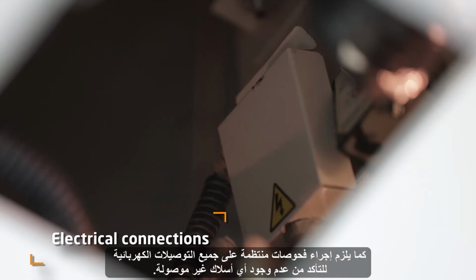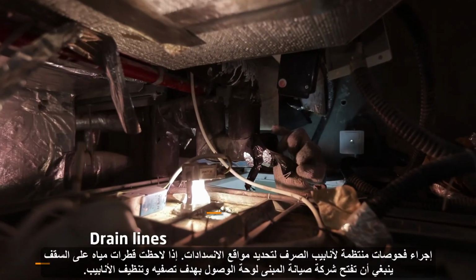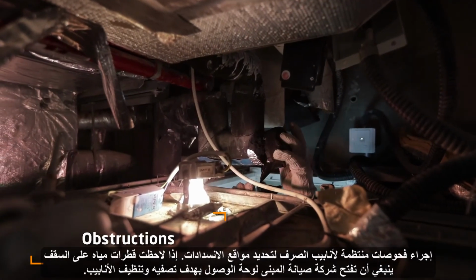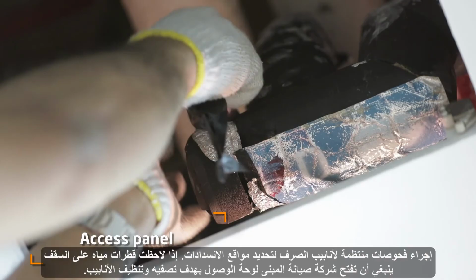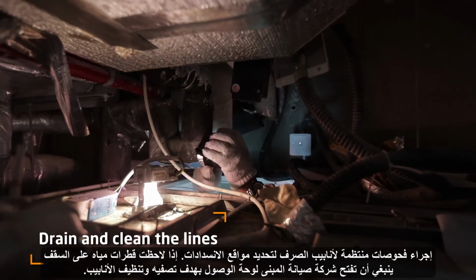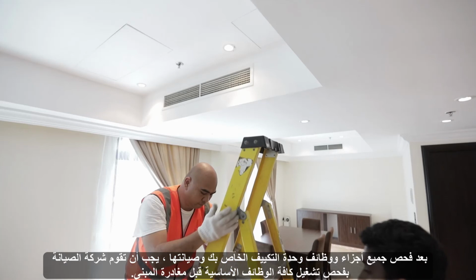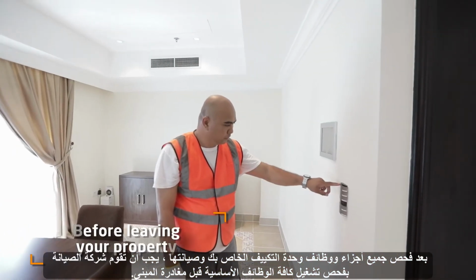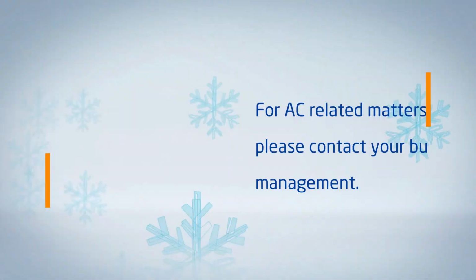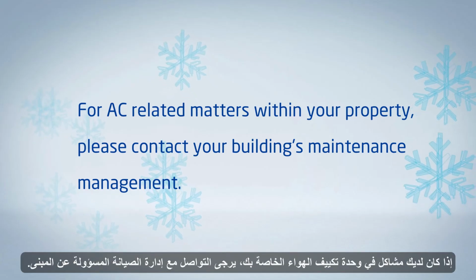Also, regular checks on all electrical connections are needed to identify any loose wiring. Regular inspection of the drain lines is required to identify obstructions. Should you witness condensation on your ceiling, the building maintenance should open the access panel, drain and clean the lines. After all areas and functions of your AC system have been checked and maintained, your building's maintenance should carry out a functionality check before leaving your property. For AC-related matters within your property, please contact your building's maintenance management.